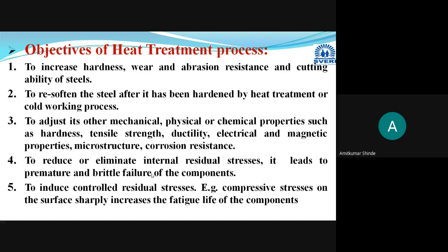When load is applied on a component with internal stresses, it will lead to premature and brittle failure. That's why you have to eliminate, or try to reduce, the internal stresses present in that component. How this is conducted, we are going to deal with in the different heat treatment processes. This can be achieved in the annealing process.